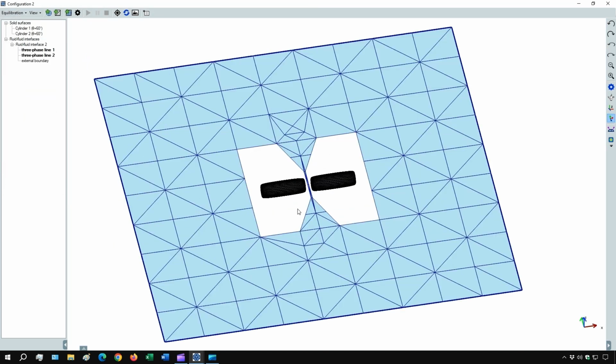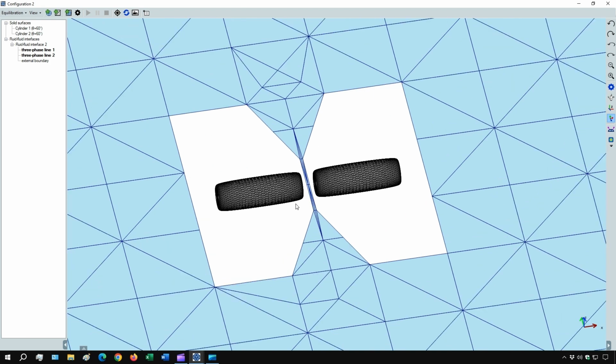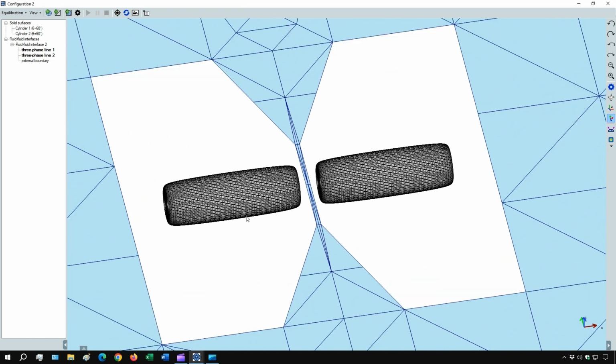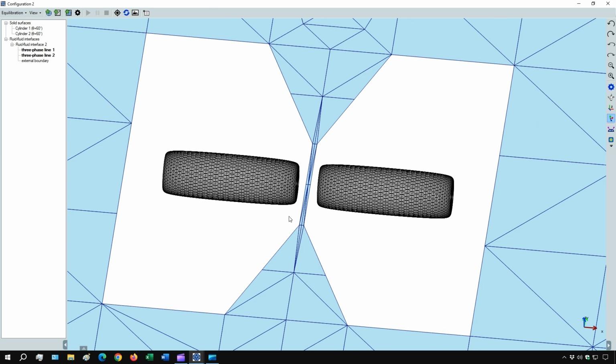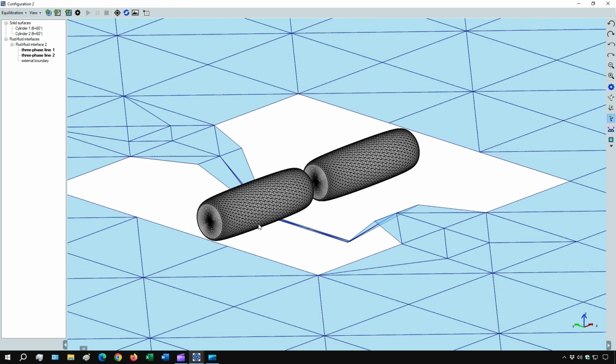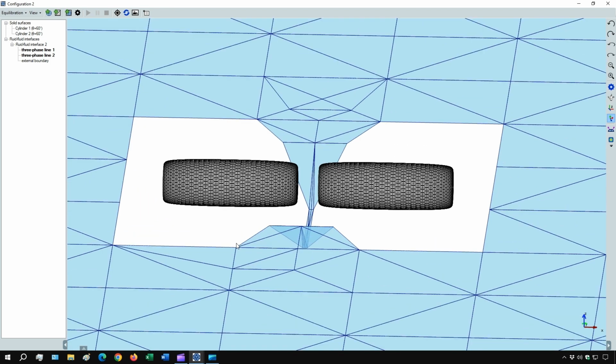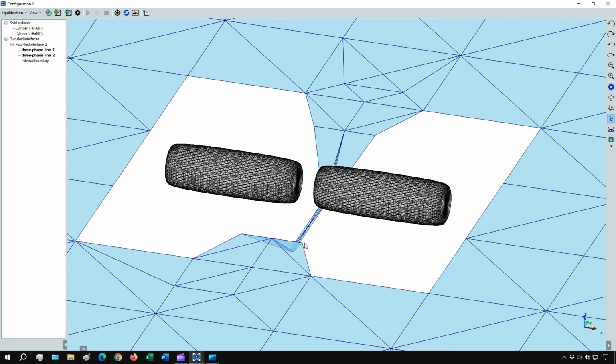For example, in this case, to avoid this problem, we can lower a bit, in between the two particles, the vertexes of the fluid interface mesh. In this way, when we select the constraint, all edges going from an inner vertex to a boundary vertex should end up staying on the external side of the solid particle. As you see, we have edited the shape of the fluid interface mesh, lowering a bit its vertexes in between the two particles.